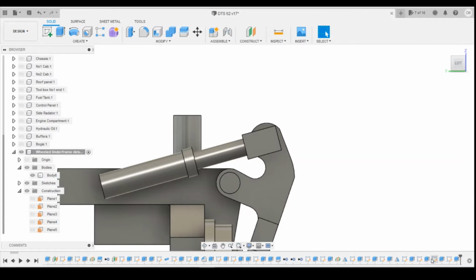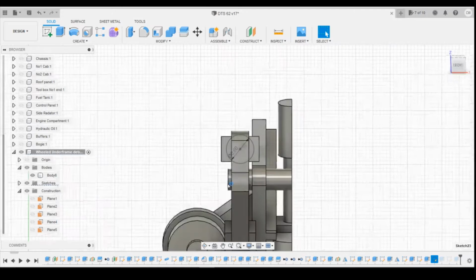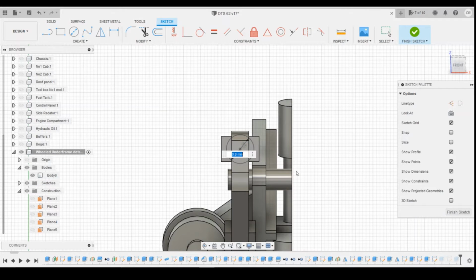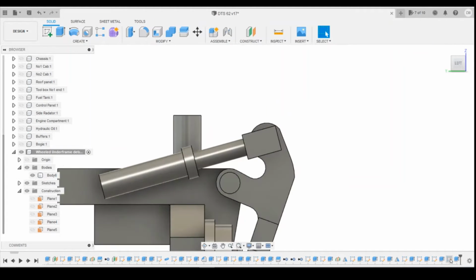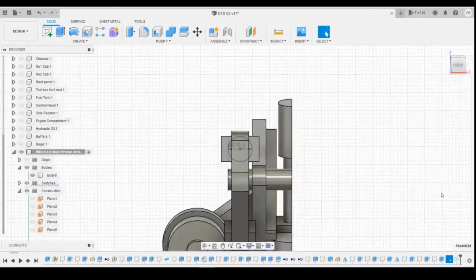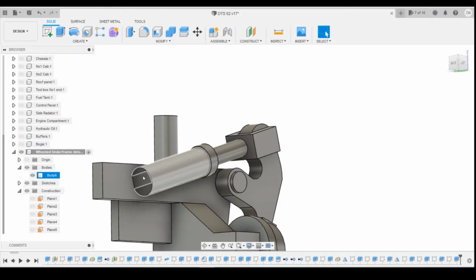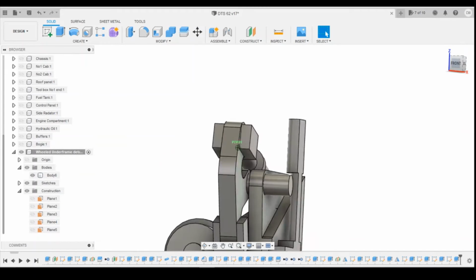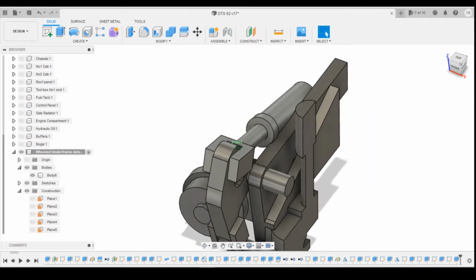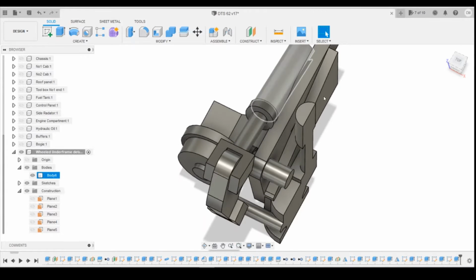Right, so I'm going to go back in here. I'm just going to change the sketch here from 0.8 to say 0.9. And then the next one, if I edit that, we'll change that to 0.8. So we're still getting the size step downs, but it's now getting supported touching the back here, so it's not going to float and potentially be too easy to break off there. Okay, so see how it cuts in the side here as well.